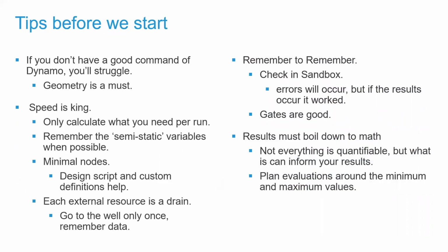Some other tips before we start. If you don't have a good command of Dynamo, you're probably going to struggle with Refinery. That may sound pretty basic, but there it is. Next up, speed is king. Only calculate what you need per run. Don't spend a whole bunch of time calculating something that you don't need right now, because when you do that, Refinery is going to do that for you 10,000 times on some of these larger studies.